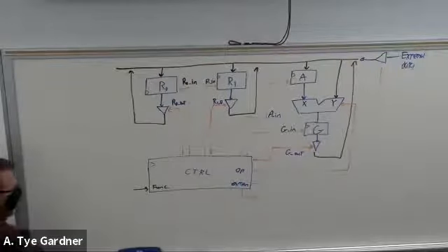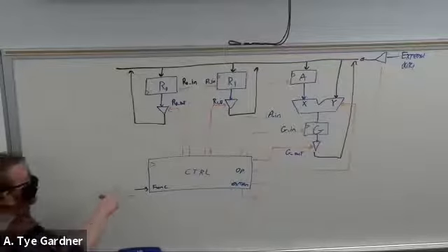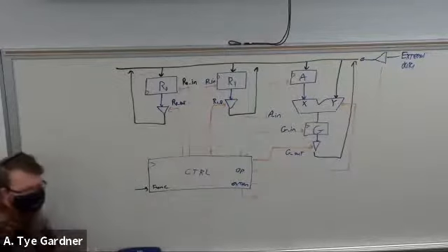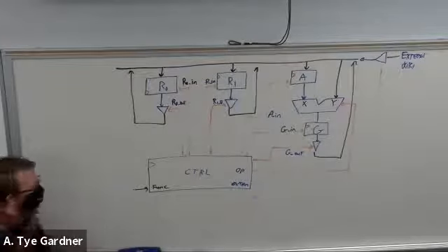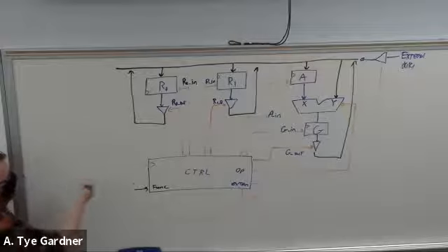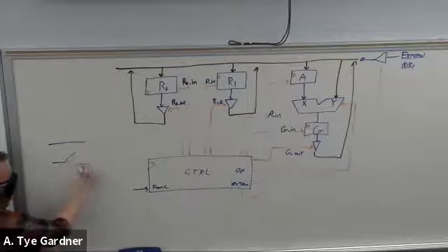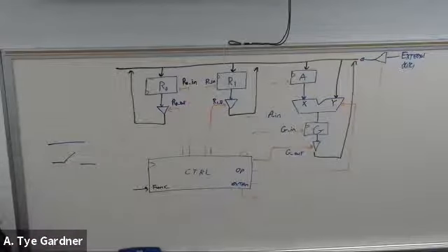Now, I mentioned in this lab, it's worth mentioning again, especially on video, that Vivado has a bit of an issue implementing this type of buffer, which is just an output enabled buffer, where the ideal situation is if it's enabled, it's a wire, and if it's disabled, it's an open switch. Well, when we write the VHDL code for that, what do we say?